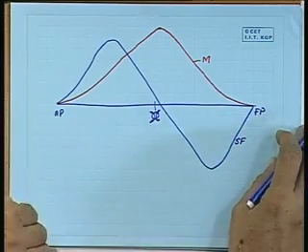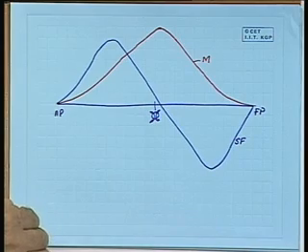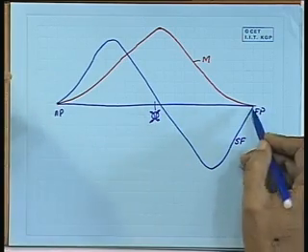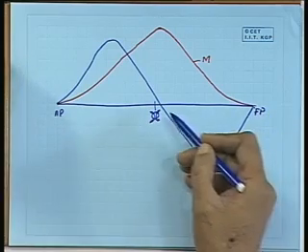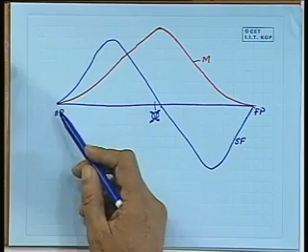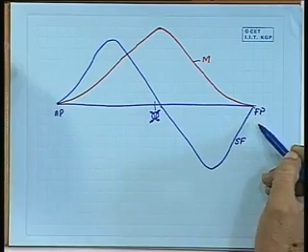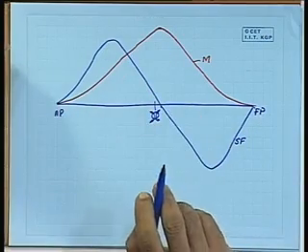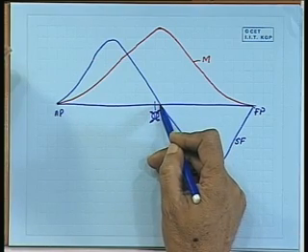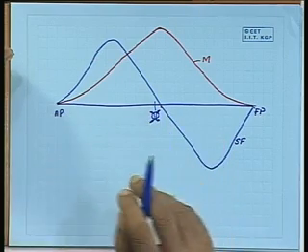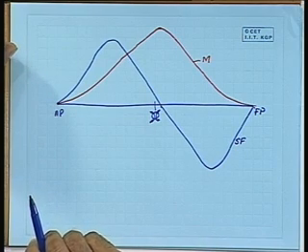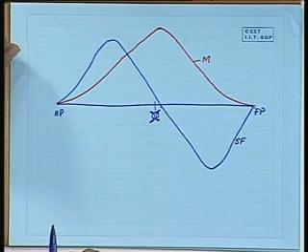Now, what we can see from these two diagrams is that the shear force is 0 at the after perpendicular, that means at the after end, also at the forward end, and somewhere near the midship region. And the bending moment is 0 at the two ends and is maximum somewhere near the midship, where basically the 0 shear force in the beam is occurring. From the mathematical point of view also, this satisfies this condition.